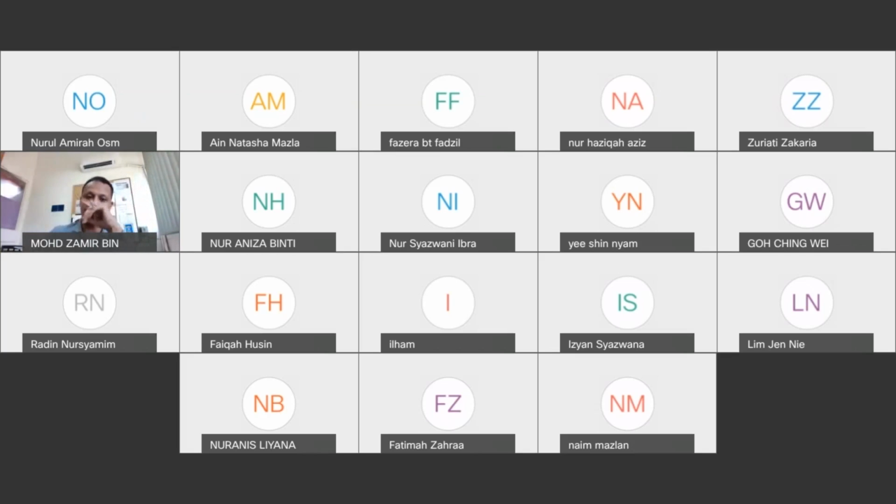But for IC fabrication, both sides must be polished, because there will be effects of surface tension or handling or robot arm capability. It will somehow affect the automation as well, even though there are no processes done on the rear side of the surface. It's more on the handling, processing, identification, sensing kind of thing, because we hardly process both sides to produce our device. Okay, Shamim, any other questions?